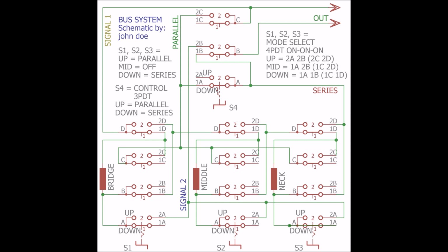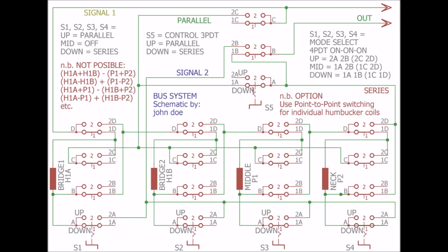The control switch can be replaced with a DP/DT switch, but for guitar setups with more than 3 pickups, with additional buses for complex compound connections, the wiring concept of the 3 PDT, as shown, may be adopted, and expanded as necessary. Unlike the other previous switching systems, the bus system is very easy to upgrade and expand to accommodate HSS, HSH, or HHH pickup configurations, connecting each coil individually, since all the components are modular.